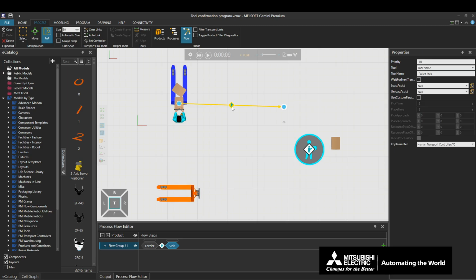This section will now explain the remaining values. Product property can be selected only in tool of the transport link. In property name, specify the string type product property defined in the product to be transported. The specified value is used as a keyword as shown before in tool name to set the tool. No tool executes the tasks without using a tool.